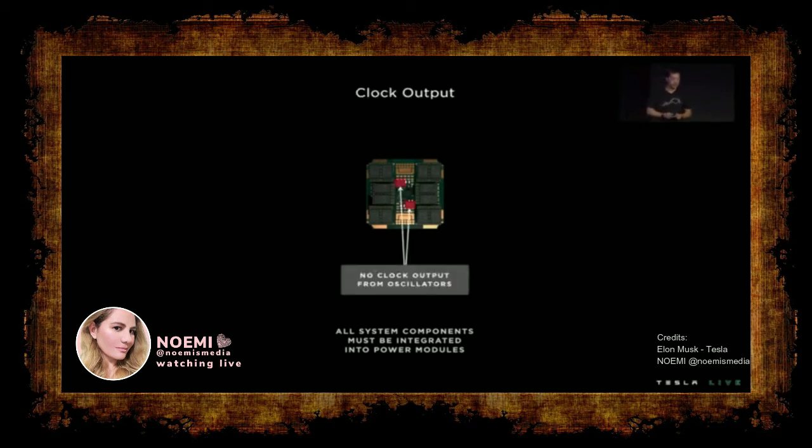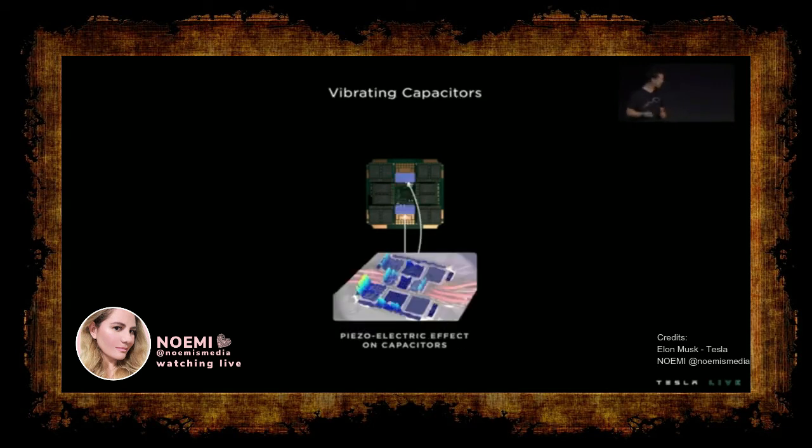In this case, the failures were due to losing clock output from our oscillators. And after an extensive debug, we found that the root cause was vibrations on the module from piezoelectric effects on nearby capacitors.